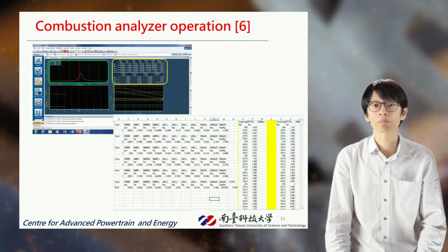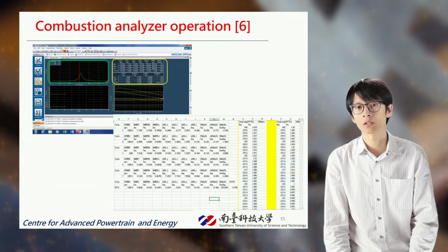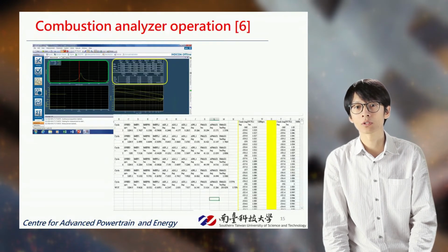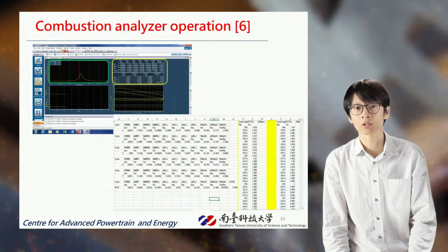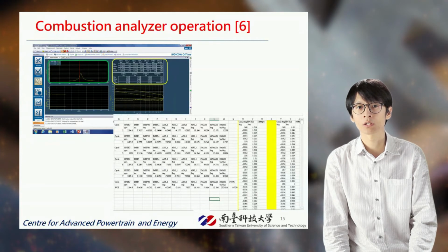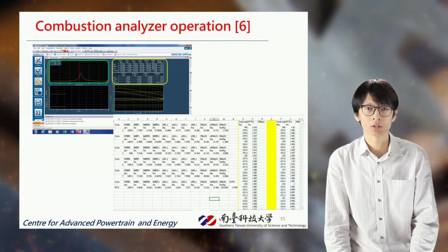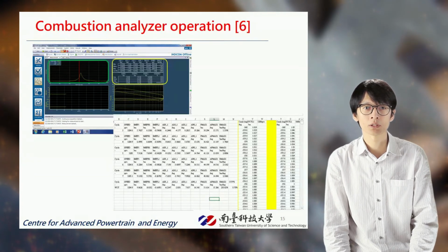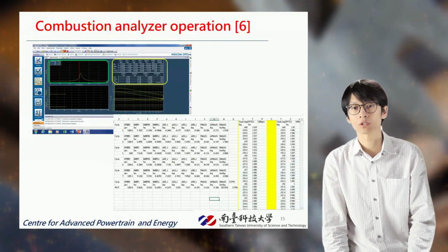Recording the data. The figure below shows a box highlighted in yellow color shows the AI value. The green color shows the PCYL that shows the pressure value inside the cylinder and determine the engine running in good conditions. Whereas the colored circle is the recording button. The yellow circle at the bottom of the figure can check the number of cycles finished.